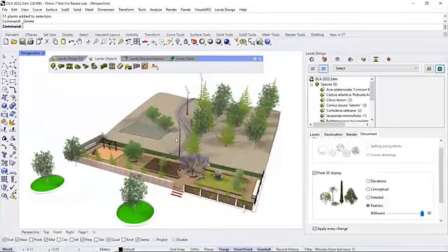What I was trying to understand is, obviously it goes from Rhino into Revit. But if we update walls, locations and things like that, does that easily go back into Lands Design? Well, then you need another definition that references those walls in Revit, deconstructs them, and generates new walls in Lands Design.